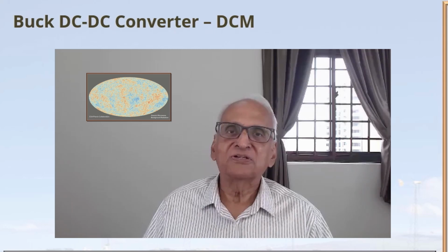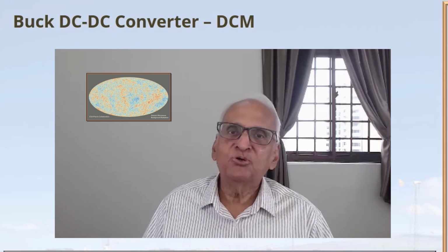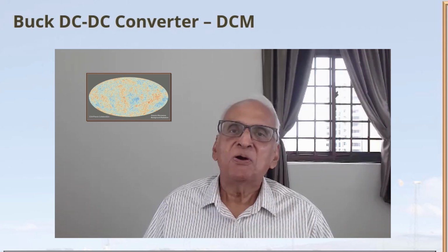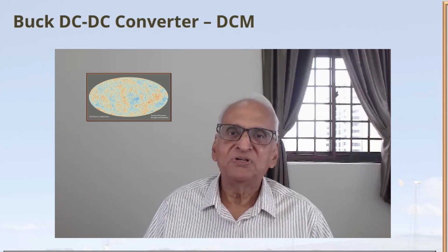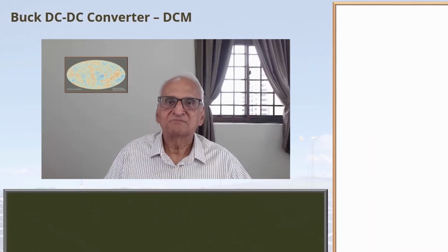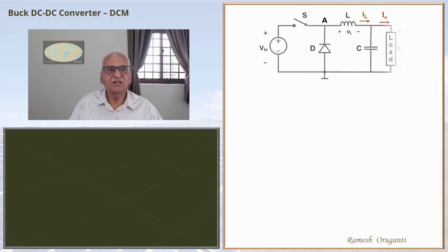Understanding power electronics. In this video, we'll go through and understand how the buck converter operates under discontinuous conduction mode. Let's get started. This is the buck DC-DC converter. When we say discontinuous conduction mode, we are talking about the inductor current. It is the inductor current that is not continuous.